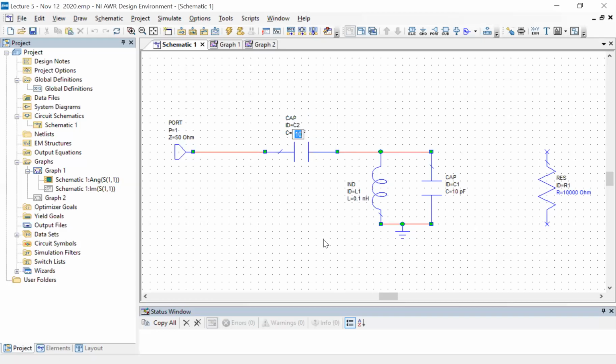So remember, the coupling capacitor is purely reactive. A capacitor is a purely reactive element, so it cannot absorb energy. And now by getting stuck between the resistor here, which is the 50 ohm resistor, the source for dissipation, you have essentially decoupled this part from this part.